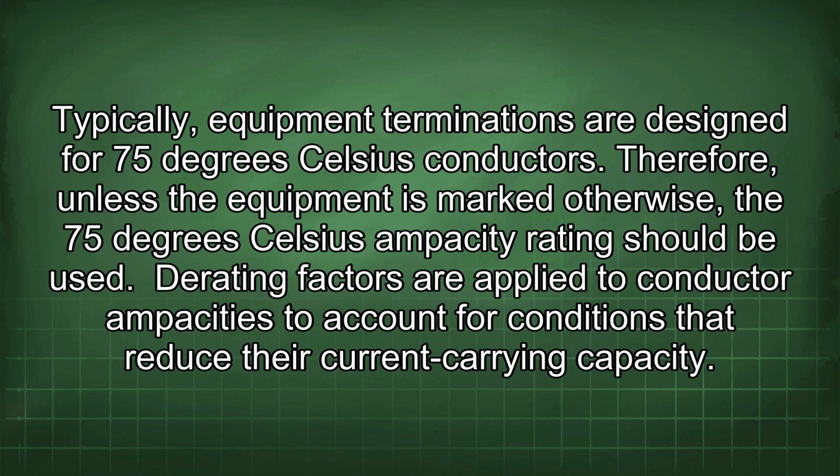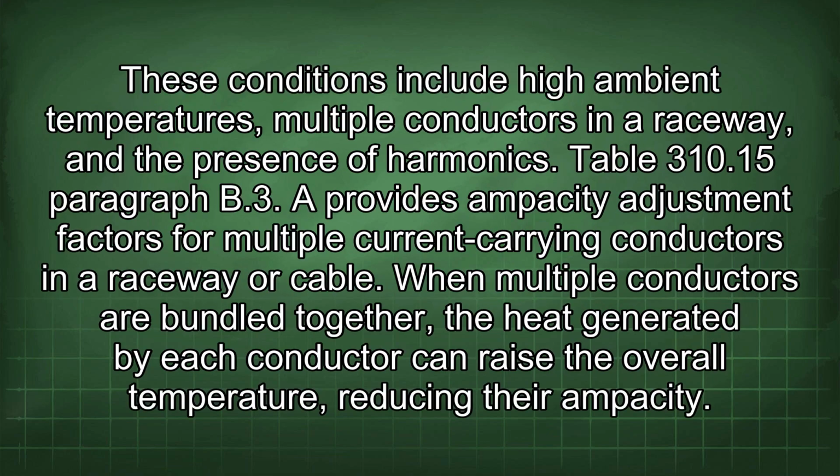Derating factors are applied to conductor ampacities to account for conditions that reduce their current carrying capacity. These conditions include high ambient temperatures, multiple conductors in a raceway, and the presence of harmonics. Table 310.15(B)(3) provides ampacity adjustment factors for multiple current carrying conductors in a raceway or cable.